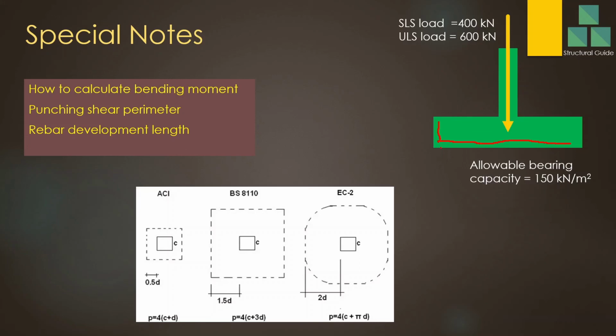But you have to keep in mind you can't always keep the bar straight. This will not be correct always. It depends. If we have high stress, you may need to bend the reinforcement upward. Anyway, if you haven't checked it, it is always advisable to bend the reinforcement in the upward direction, then there is no issue.